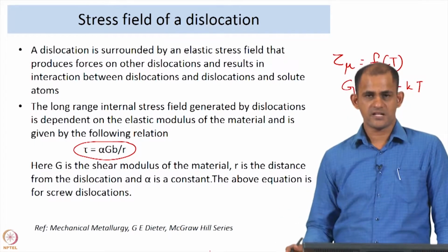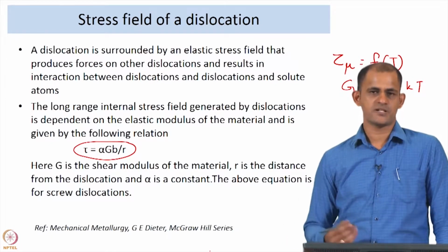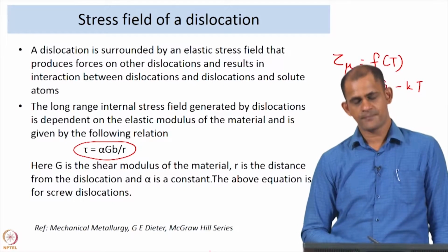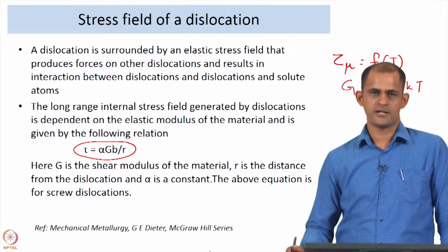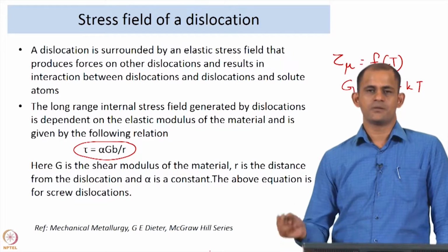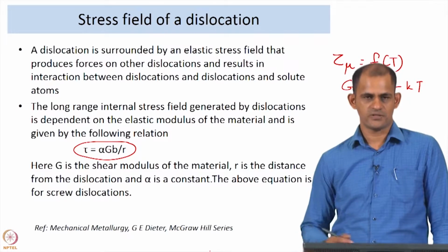the dislocation arrangements might change, and the change in dislocation arrangements and configurations is something I am going to talk about in the subsequent slides. It also means that when you are evaluating this internal stress field or the thermal component of the internal stress field, you will have to account for the fact that the dislocation substructure or the dislocation configuration should not have changed.